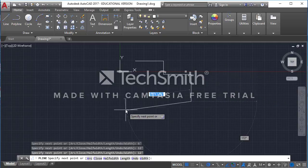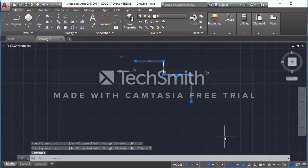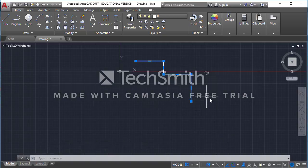So right now I'm still using the line command. I can continue to draw additional lines if I want to, but I'm always going to exit a certain command by hitting the escape button. So I'm going to hit escape, but now notice if I click on this, the line is one continuous line. You'll have to judge for yourself when it's appropriate to have one continuous line versus having multiple instances of line.